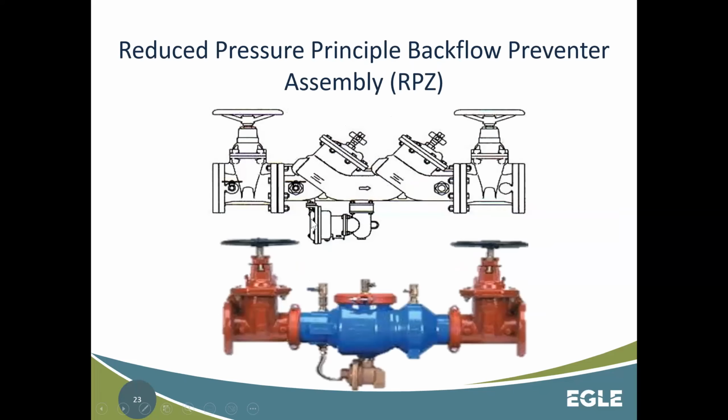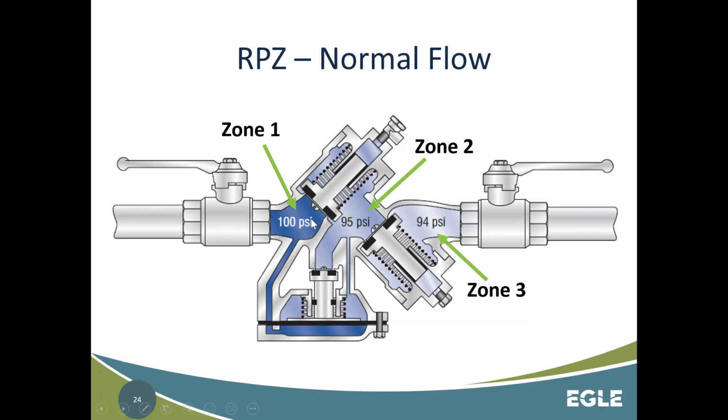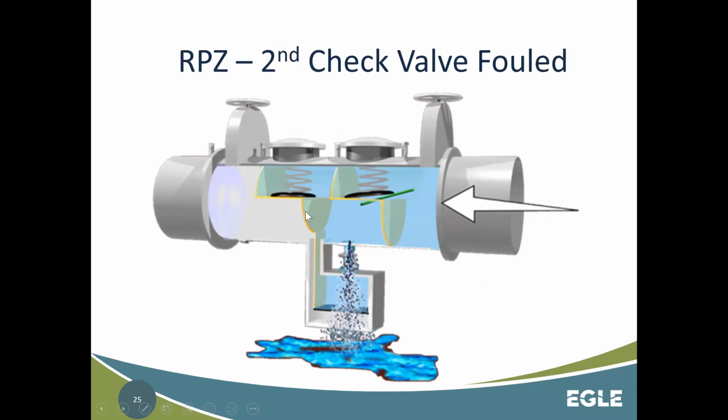The loss occurs on the first check valve, just so we're aware. The second check valve has very little weight. So all of the pressure loss is due to the very first check valve. The second check valve in here, you could push open just real easy with a finger. It's pretty easy to do. It has not much pressure against it.